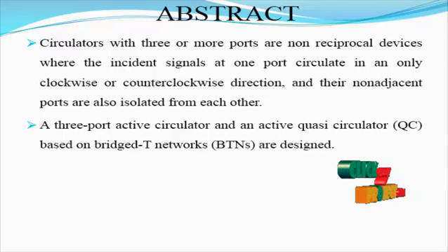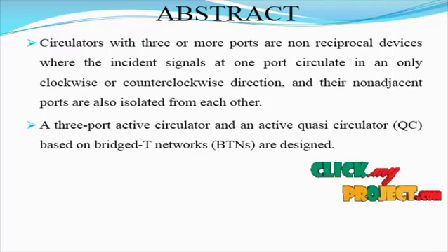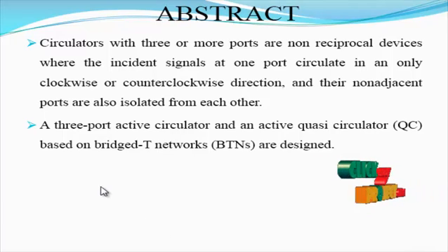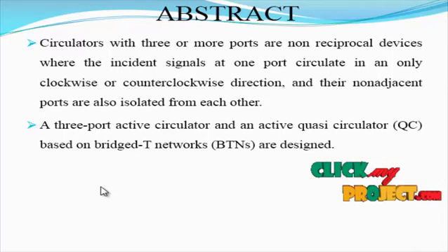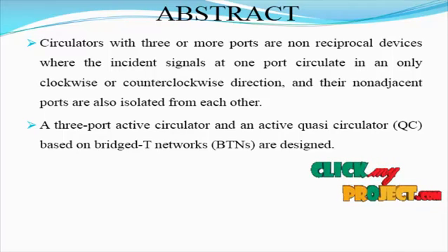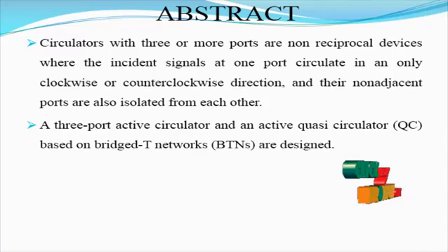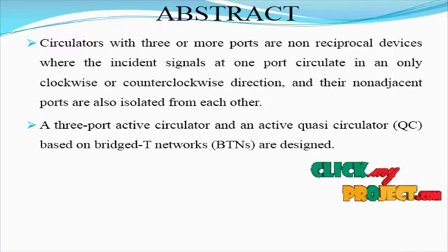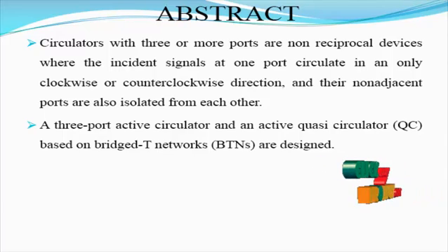In our product, we have designed circulators and quasi-circulators with bridge T networks. To eliminate the use of ferrites, the use of non-reciprocal characteristics of transistors for an active circulator was first reported. The 3-port circulator with 3 MHz operation frequency used 3 transistors in a ring-type configuration.